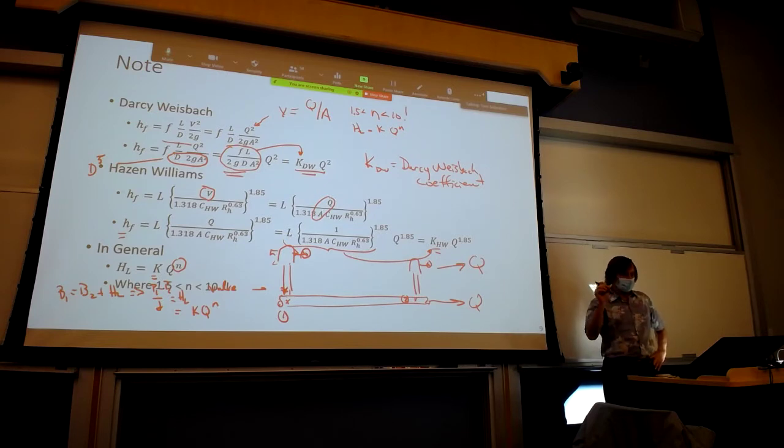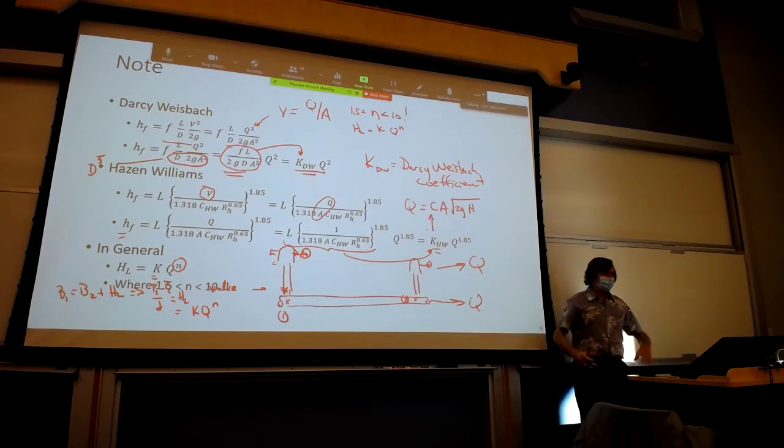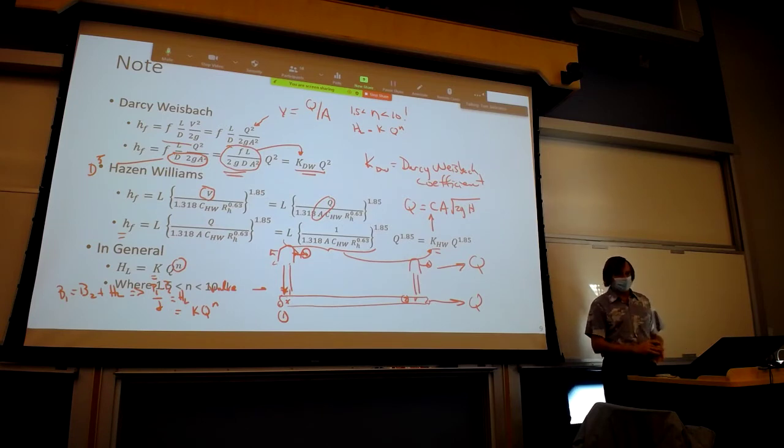And that's why, in the Torricelli equation, if you remember it, the orifice equation, what's happened is you've dramatically increased C. And so that C is representing all the energy losses in the system. So that's how we practically fold in either Darcy-Weisbach or Hazen-Williams when we're looking at systems and you actually don't know what's underground. All you're trying to do is develop a model that reflects what's happening underground.